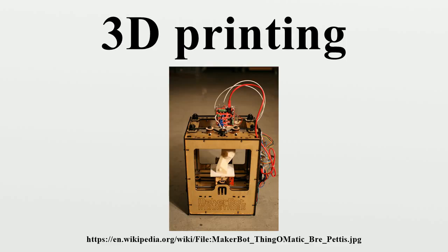It is also possible to use conventional gas metal arc welding attached to a 3D stage to 3D print metals such as steel and aluminum. Low-cost open-source RepRap-style 3D printers have been outfitted with Arduino-based sensors and demonstrated reasonable metallurgical properties from conventional welding wire as feedstock.